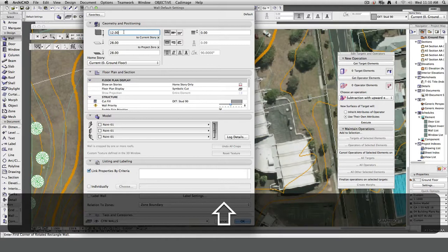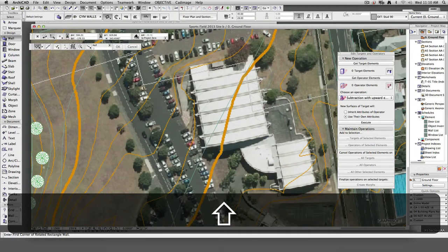Remember the settings are slightly different. Here I set the base height of the wall and how high the walls are, whereas in the normal little toolbar, you set the base height and the top height. Okay, same thing, just two different ways of thinking of it. That top height I need to know later on for setting the height of my roof.